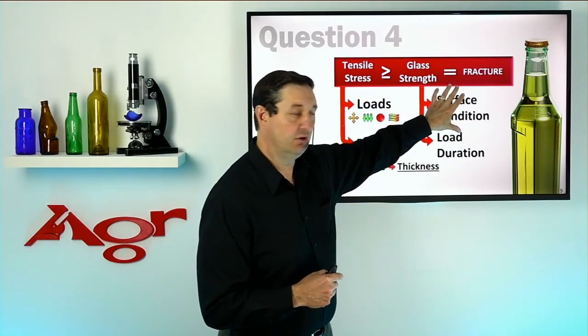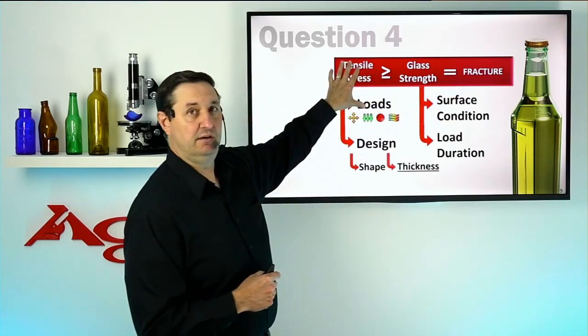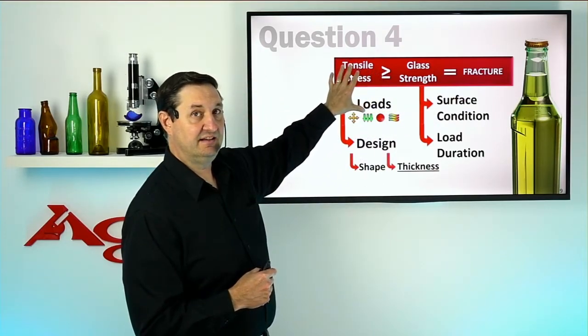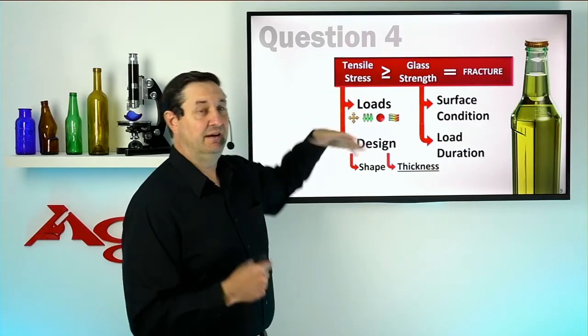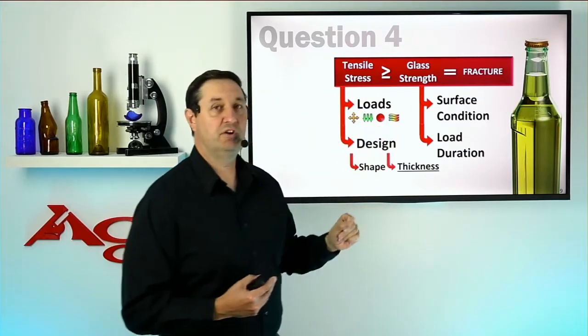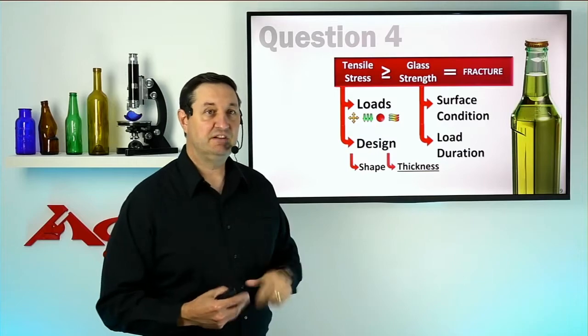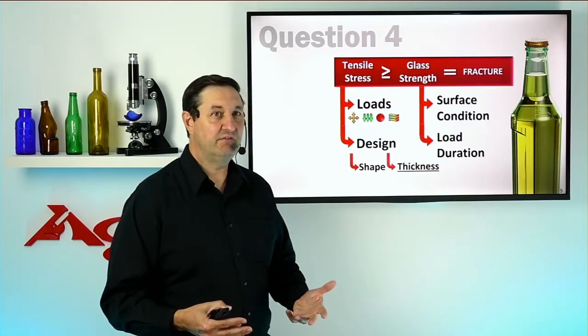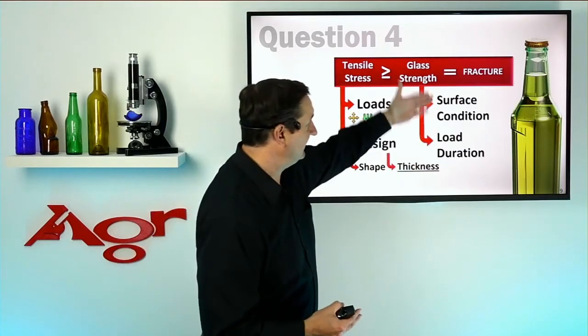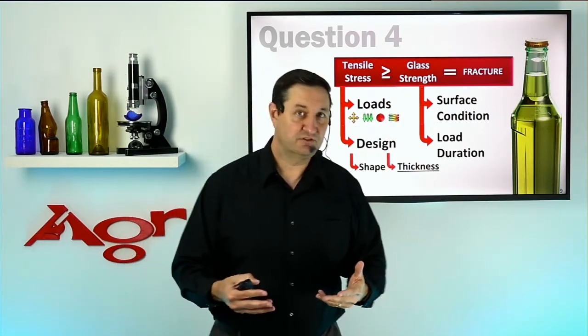We're going to input that into the program and be able to then determine how much tensile stress this thing can take? And that will set the level. Again, specific to what loads we put on that container, how that bottle is shaped and designed. So we have a uniqueness for every bottle, but it's all going to be dictated on our knowledge about those glass surface strengths.